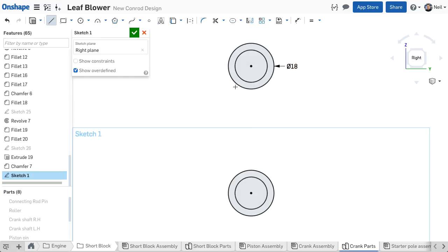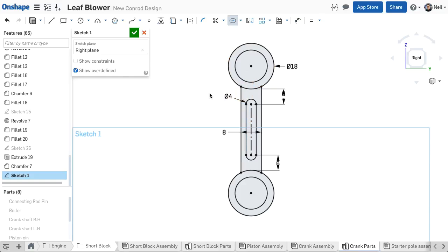You can continue to sketch to build up a layout for the part or parts you are creating, such as the shank that connects the two ends. Hovering your cursor over entities in the sketch will wake up geometric constraints, allowing you to create relationships on the fly and complete sketches fast. You can put all your detail in one sketch or add them to the model as needed. To remove weight from this part, the slot command is the perfect solution.